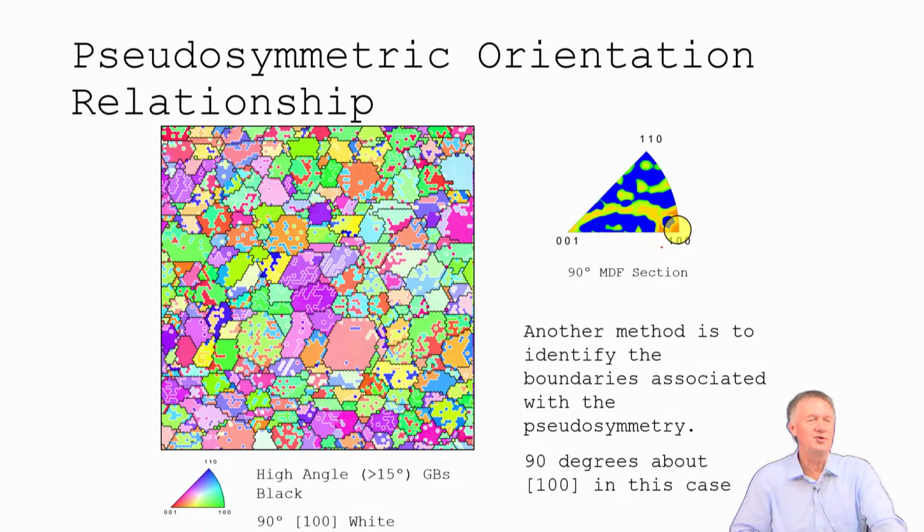So the work that is being done recently using dictionary indexing and spherical indexing is one way that you can determine very small shifts in the pattern, and it has actually shown to be very accurate in determining things like lead zirconate titanate.